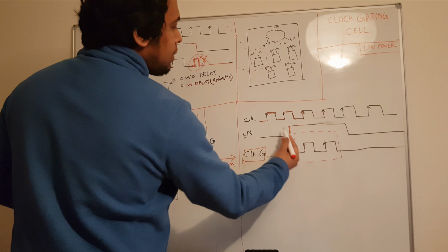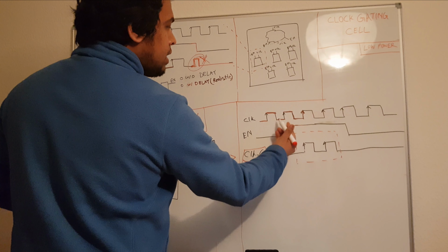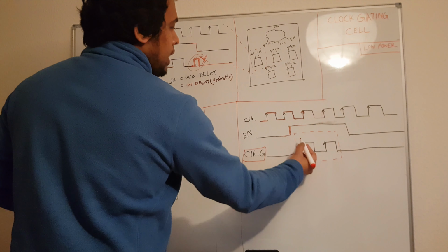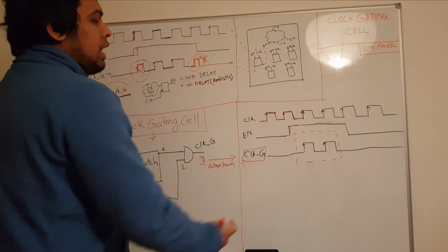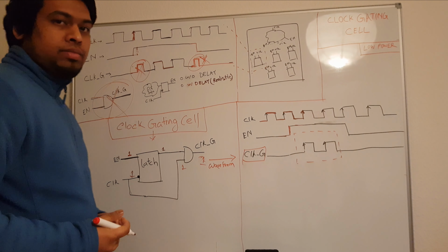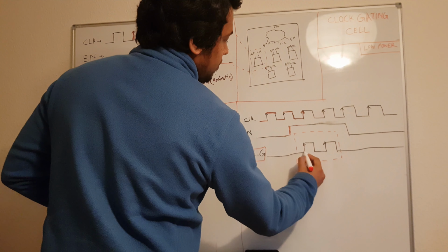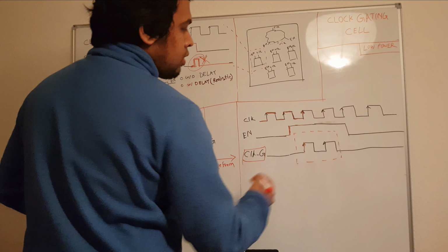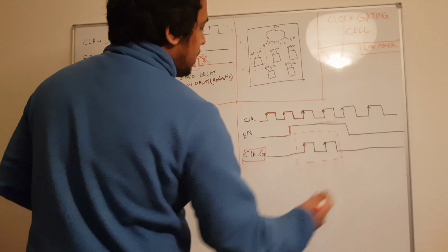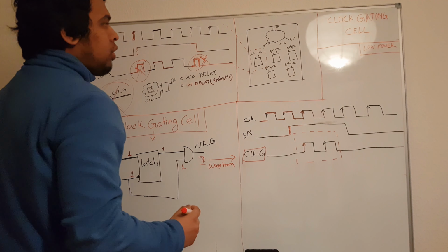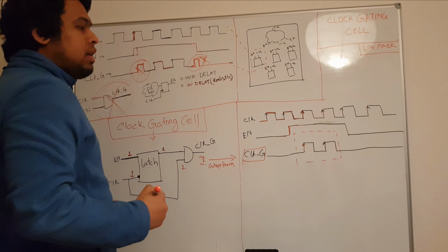we triggered the enable signal in the previous clock cycle, so that for the next clock cycle our submodule will be activated, right? So our submodule will be activated from this clock cycle, because from this clock cycle it's getting the pulse, because this gated clock will be operating these submodules, right?